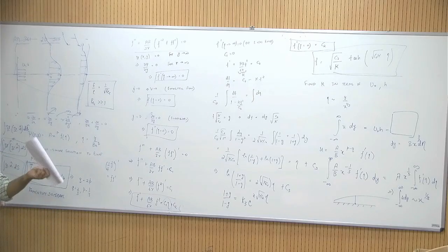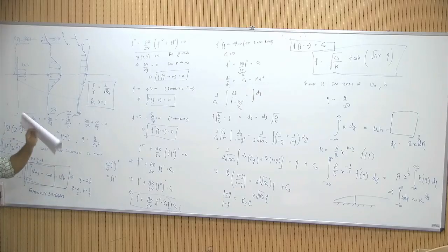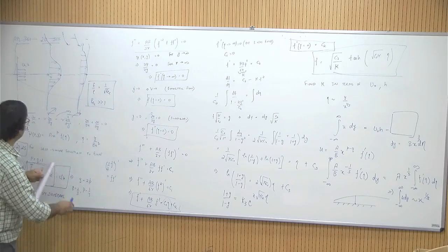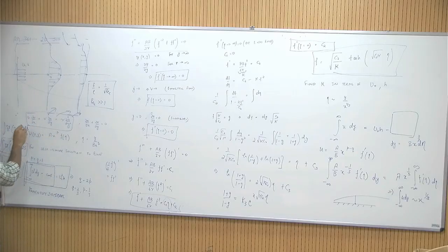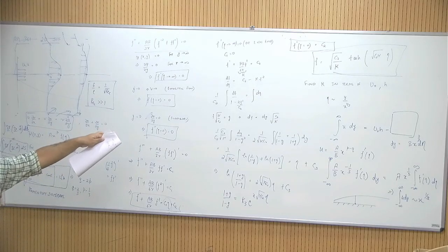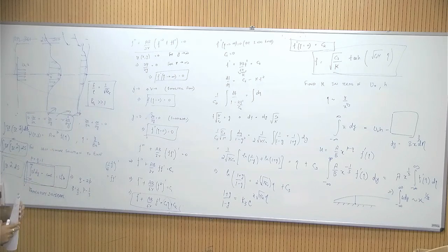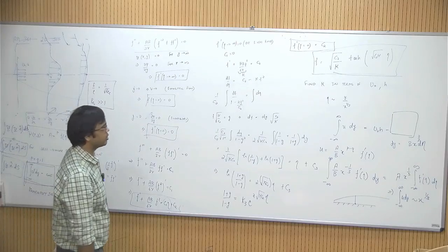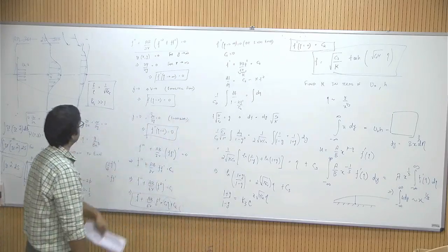Okay, if you have a jet of air coming inside vacuum, then in fact even the pressure you cannot assume to be constant anymore. If you recall this equation here, we dropped the dp dx term. Why did we drop the dp dx term? These are free jets. The atmospheric pressure is p and that is constant in x, and so once we reasoned that dp dy is 0, we said that dp dx is also 0. If your dp dx is not 0, then you have to account for that term in your jet equation also. Okay, so in vacuum we cannot expect all of this to hold.